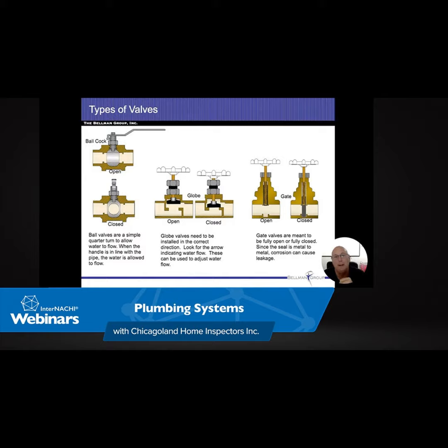Sump pumps. This is a typical pump. I'm a firm believer in battery backups as well. Most of them are going to be electric powered. There's going to be some sort of a float valve in there, so once the water gets to a certain height, the pump automatically turns on and pumps the water out.